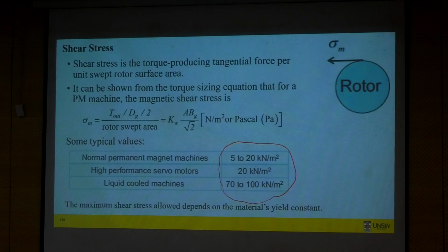And in the case of IPM machines, in the rotor, let's say I just take a conventional IPM. This part is iron, and this is usually highly saturated. It's called a bridge. IPM machines have bridges, okay, iron bridges.